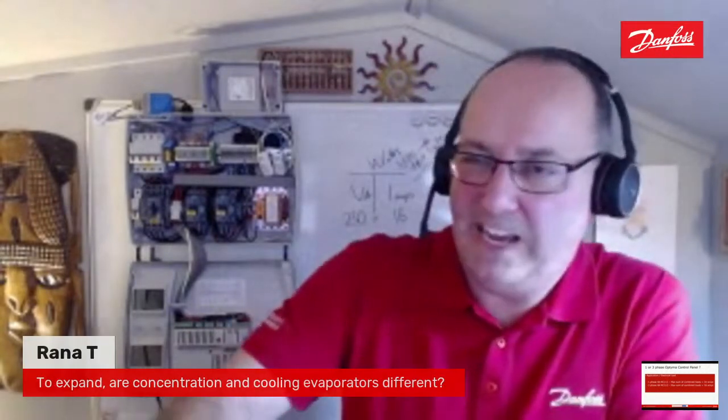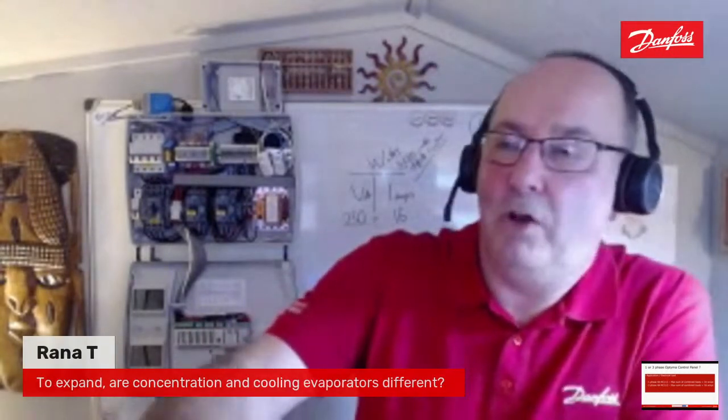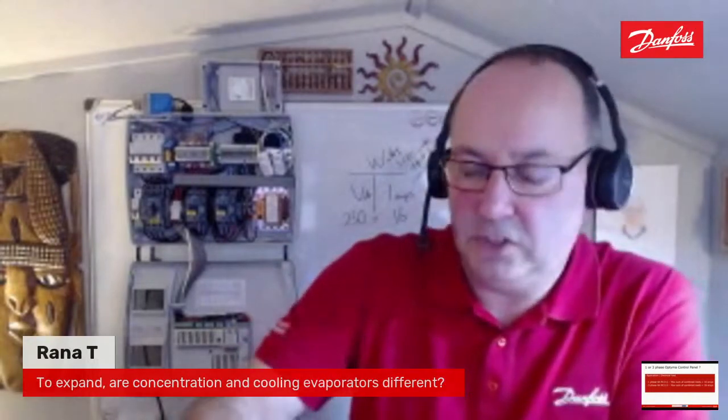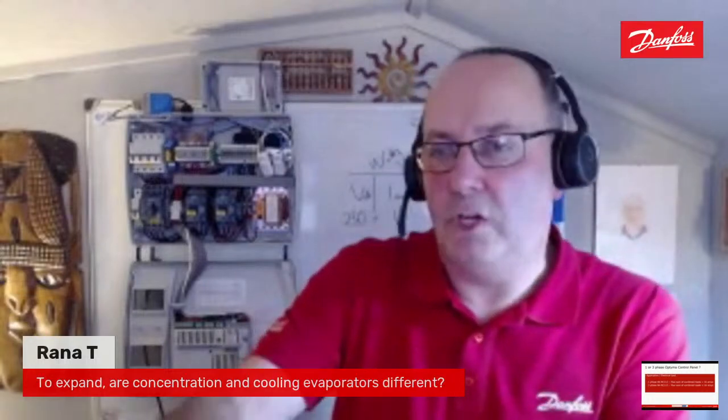For example, if it was a milk tank, don't run the refrigeration system until you have reached your minimum fill point within the tank, so that you actually have some load back to the machine. Otherwise, if there's no load, let's say a small amount of milk before the minimum fill point, then your machine will go on LP because there's no load for it there. So, there's lots of differences, basically.